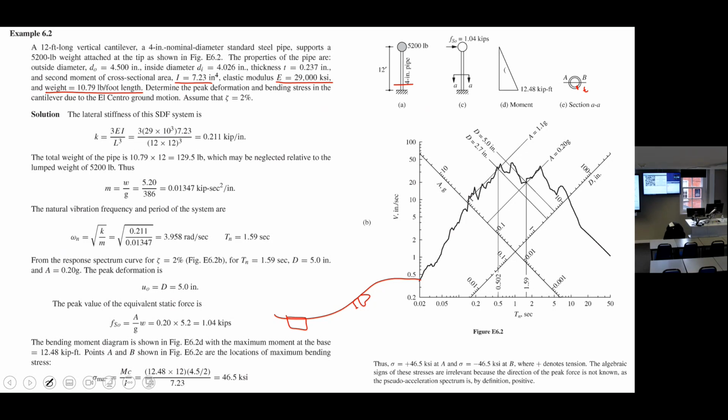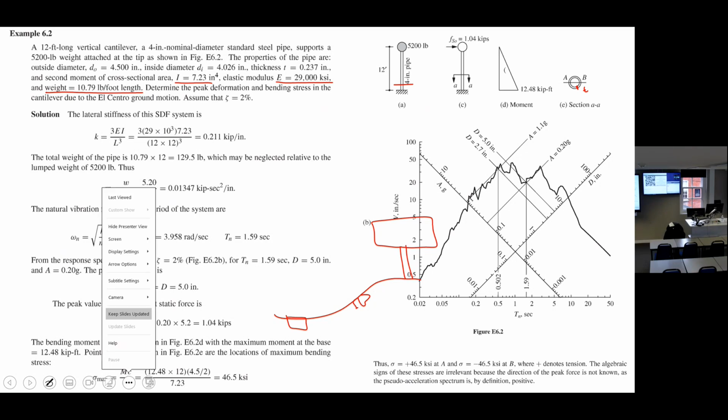The second solution is to put some water tanks around, and you pump water once to the tanks and turn off your pumping stations, and the water goes to the residents by gravity. They are up at the residence, you know, they're elevated. And when it's finished, they pump again. Okay? So you don't need to continuously pump water to everyone. Right? So you can supply water pressure for everyone with this trick.